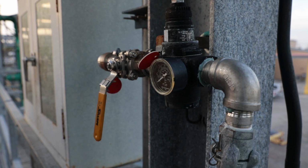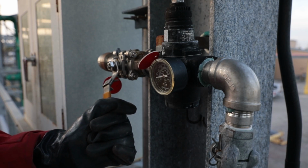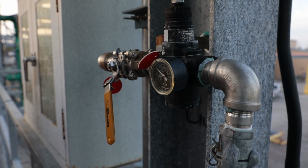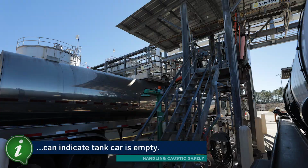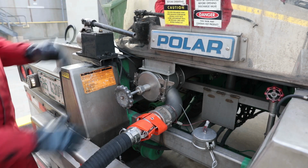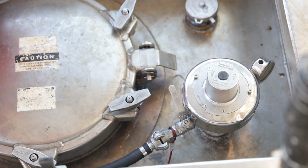Slowly open the air valve to pressurize the tank truck to about 15 to 20 psig. Do not exceed 25 psig. The sound of rushing air or a drop in pressure can indicate that the tank truck is empty and that the transfer is complete. Close the unloading line valve, if any, and the external valve on the tanker as soon as possible. Close the truck's internal and external valves.